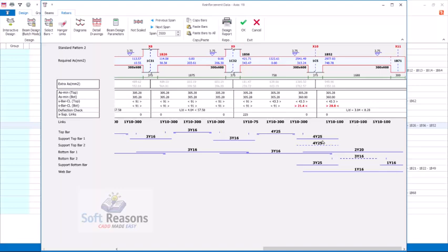What we are having here is just the spacing. What you do to this spacing, you can add another reinforcement here. Here seems to be a cantilever, so you increase this reinforcement to y20 and then make it like 3 or 4 options of that.